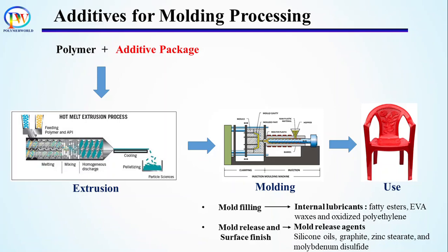of the equipment. But the concentration of these additives is very carefully decided since it may cause some negative issues like flashing due to low melt viscosity and also blooming of the additives on the surface of the final product.